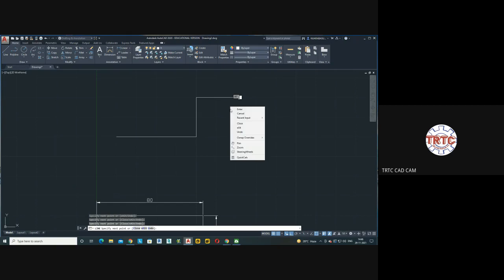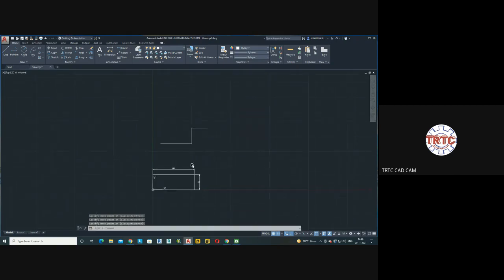Okay. So it is very easy whenever your sketch is of some multiples. You don't need to worry about the dimensions. You can simply turn on this grid, turn on the snap. You can stick to those points.